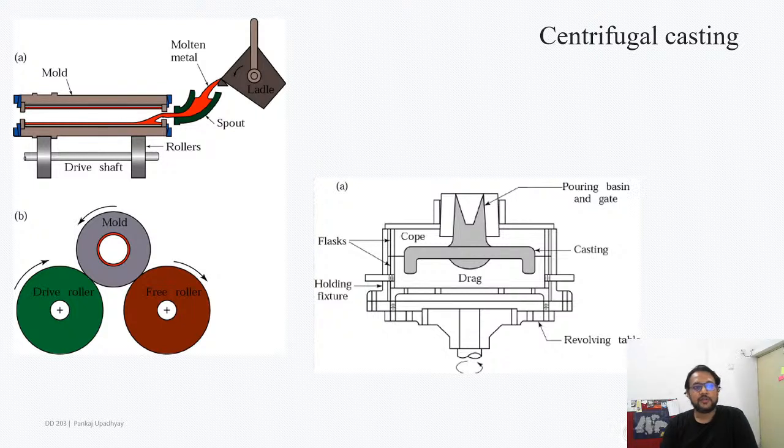Okay. Anyway, beyond that, there are some specific processes, like for example, you can always cast tubes by having this kind of a setup where the mold is rotating and you pour the molten material on it. It coats the surface, you remove the excess material, and you would have a cast pipe, and it will be very strong. I think it is much stronger than these welded pipes where there is a clear seam, but I'm not too sure. Okay, but anyway, this is a process that is there. You could do this with any kind of molds or designs where the shape is symmetrical. Okay, actually symmetrical.